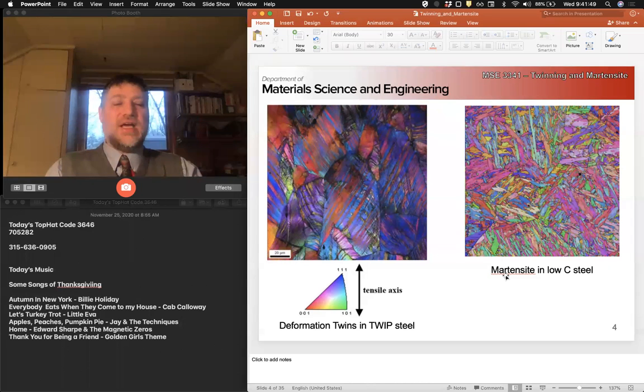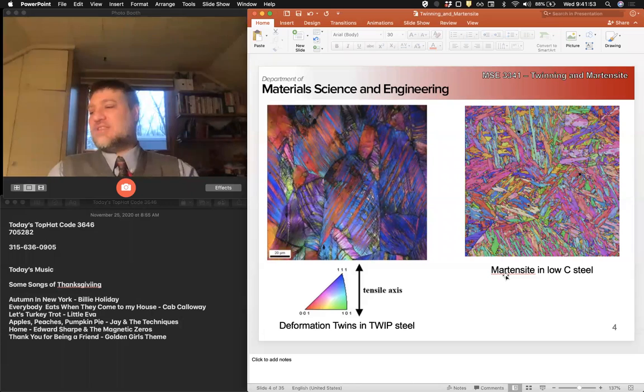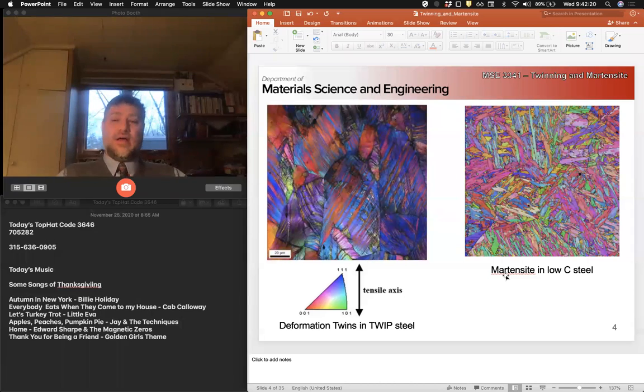And this can be effective enough that we can have operating temperatures inside a turbine engine that actually exceed the melting temperature of the blades, of the nickel superalloy in the blades, right? Because of this combination of active cooling and thermal barrier coating, right? The challenge in developing this technology was that zirconia undergoes a martensitic transformation. It transforms from cubic to monoclinic, right?